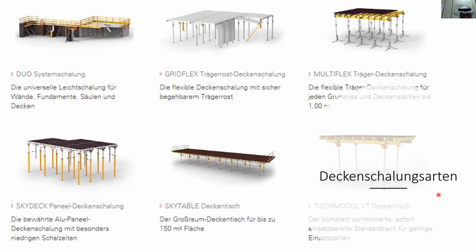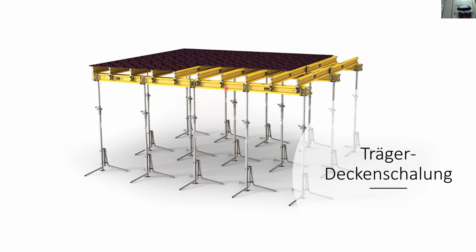So let us look a little bit more closely at these different types of formwork. This is, as I told you, the easiest one. This is also the cheapest one in terms of material. There are just these steel columns which can be adjusted in height. They are fixed, so they can be erected easily. They will not fall down. And then you put the main girder, a wooden girder, in this direction. And then on top, you have a secondary girder going in this direction.